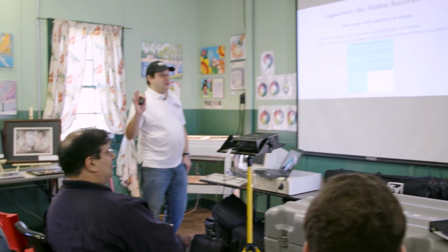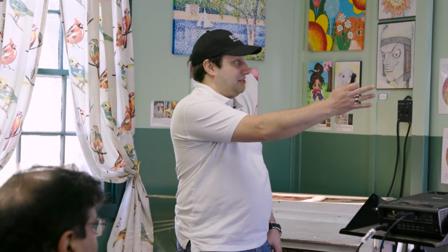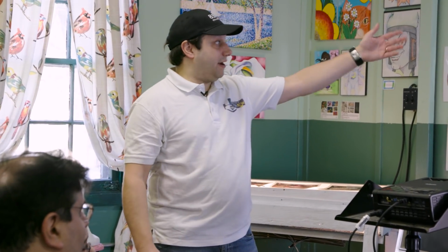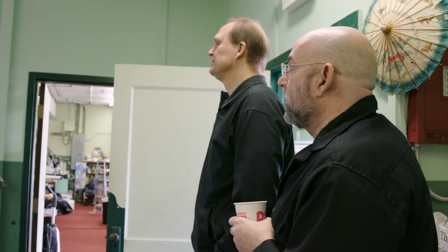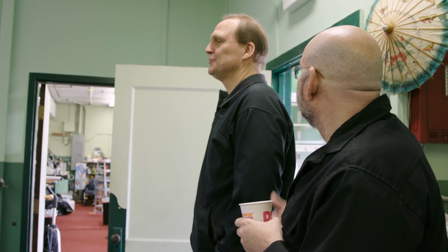I've never had my audio go out on my machines. I have heard this happen where audio on an Amiga goes out, and it's because of a polarized capacitor in the audio circuit. And this guy has a whole write-up. If you polarize that, if the negative goes towards the load, it should be okay. But they may have used a bad kind of cap or something. It could be. I don't remember.